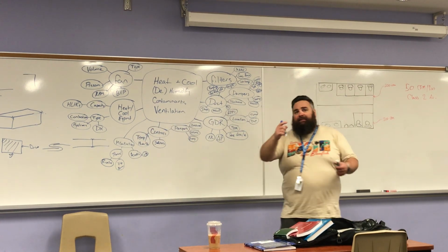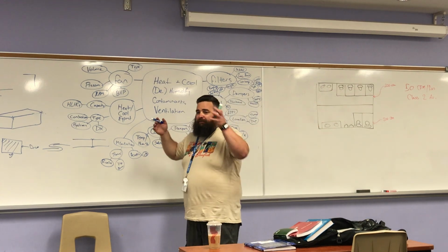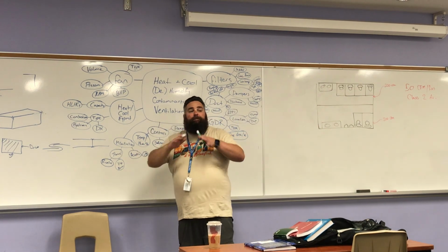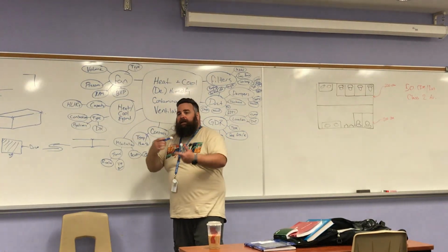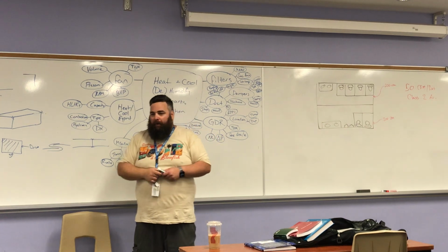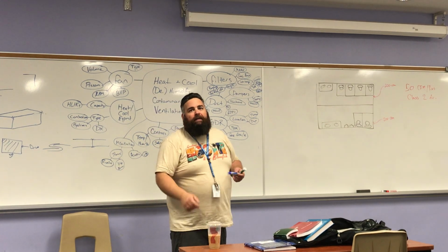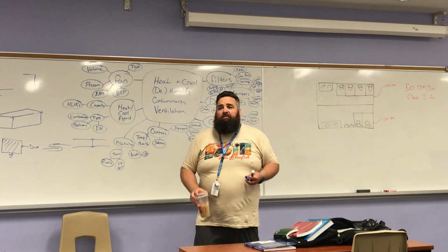So that egg crate, I can't just put it in the ceiling above the bathroom and call it a day. I have to build a metal box to put that egg crate in. I have to connect the duct to that metal box. So there are these ancillary costs that can creep up on you. How much does it cost? That egg crate there is probably about $5.